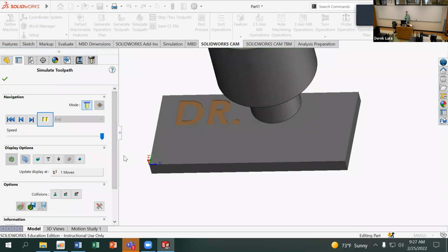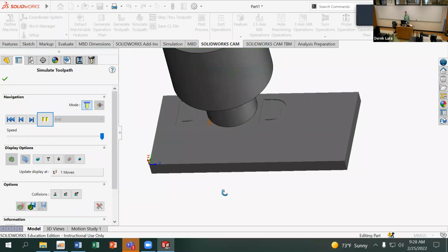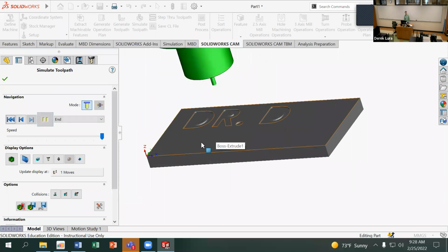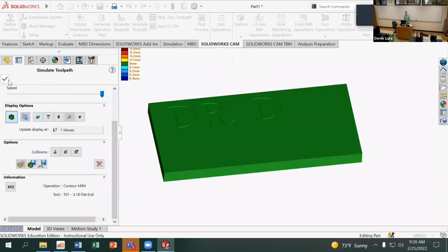That is a really bad toolpath. I probably would take off that operation if I was trying to get this to actually work. That path is real bad. It's probably that second roughing operation that I just don't need. I'm also not sure. Oh, it's doing a pecking operation. I don't like that at all. I'm going to ignore it though.